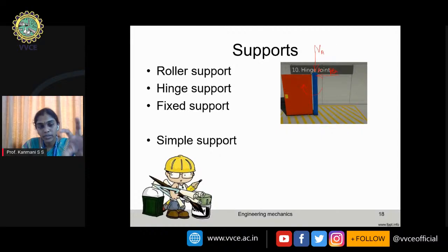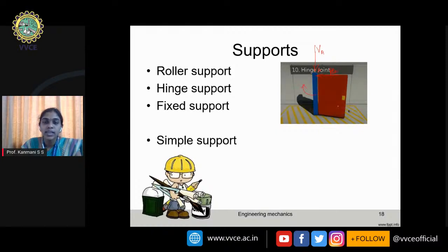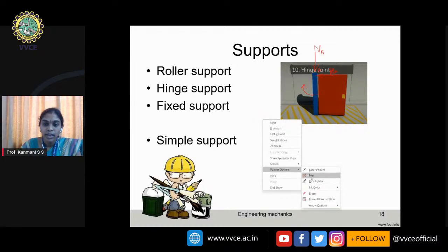whereas the other reaction, that is the moment, the rotation, is allowed at a hinge. So only two reactions at a hinge: one is VA, another one is HA. Only two reactions at a hinge support. That we should remember.